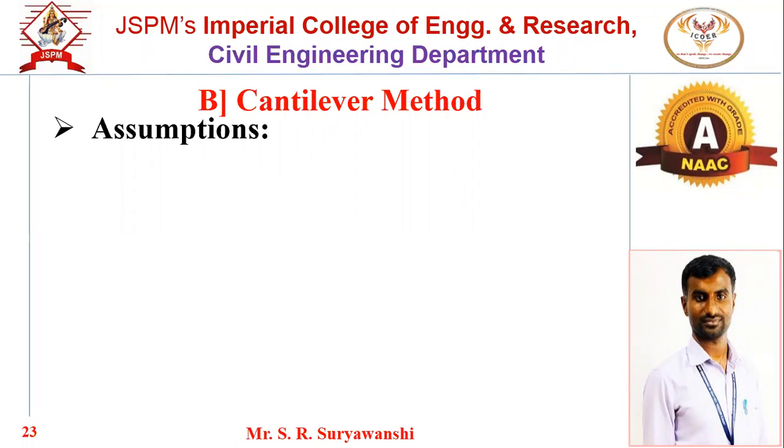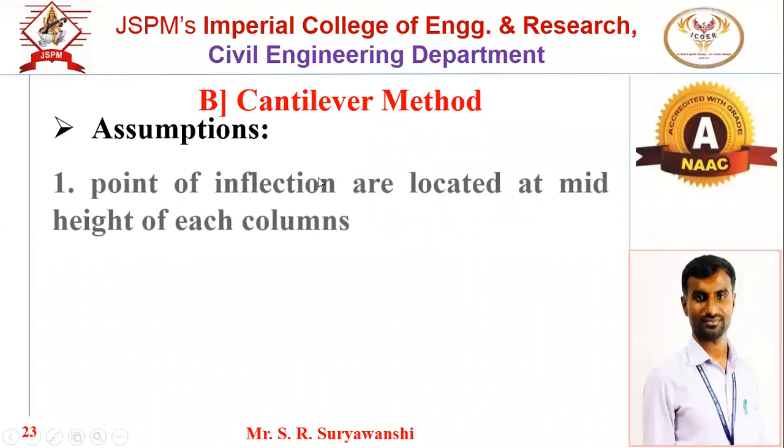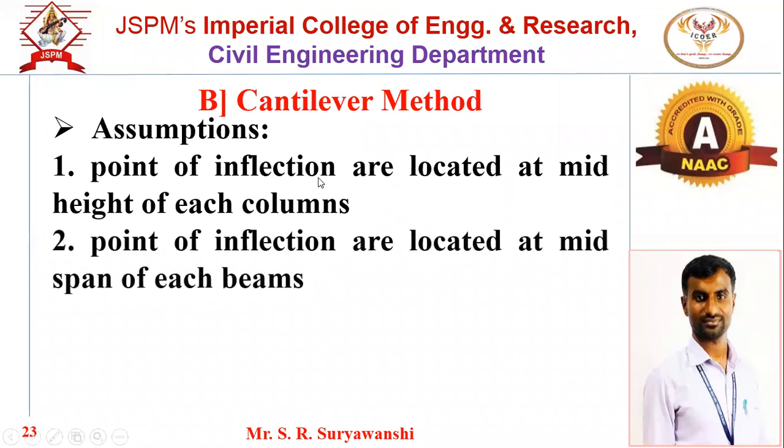Asha, tell. The second assumption is that the point of inflection is located at mid span of each beam, as that of column it is located at mid height, and for beam it is located at its mid span. These are the first two common assumptions for both the methods: mid height of column, mid span of beam, point of inflection will be there.